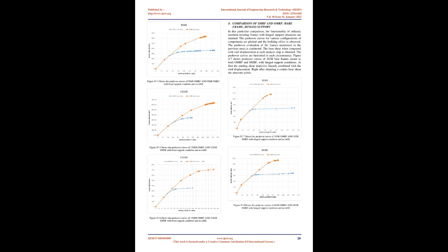At each step, the structure is pushed until enough hinges form to get a curve between base shear and roof displacement of the structure, widely known as the pushover curve. At every phase, the total base shear and the relative roof displacement are plotted to obtain this pushover curve. It gives us an idea of the maximum base shear that the structure can resist and the related inelastic drift.